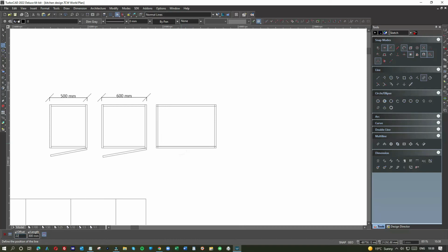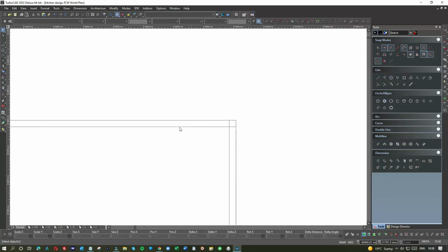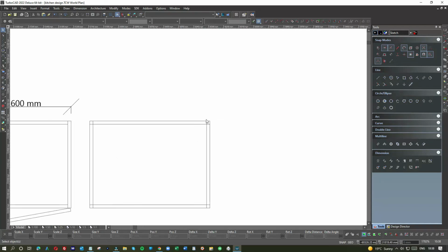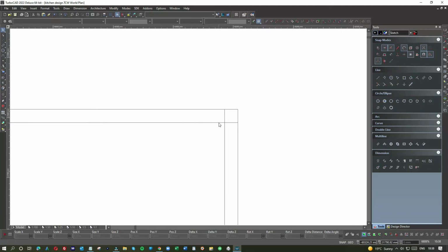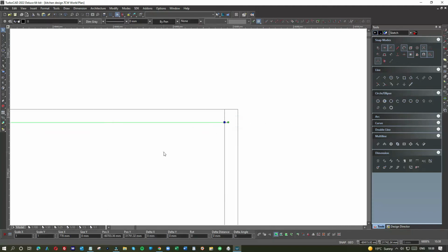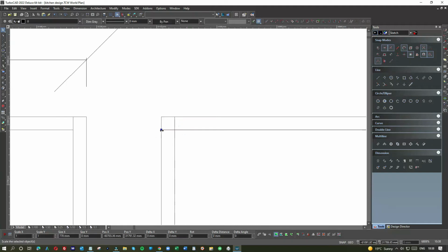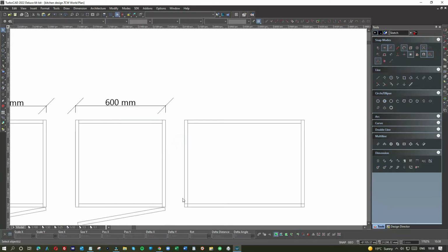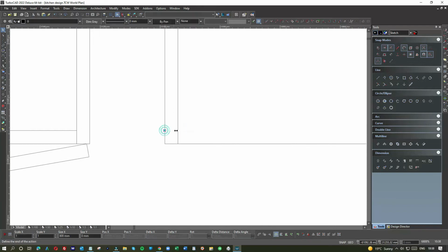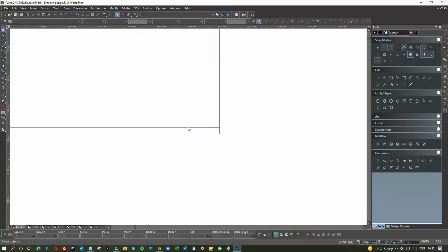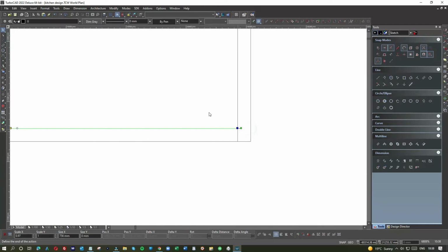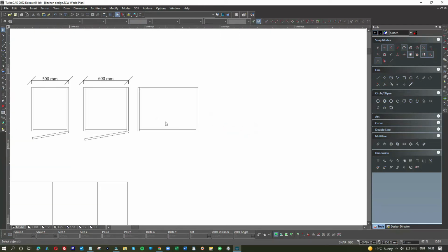tab 22. Now, kitchen units are generally assembled like this. You have two short bits in the middle, and these are full length, in other words the 580. So they would look like that once assembled, with the attachments coming through here, screws, etc. They use dowels, and a kind of catchment tool, one that fits into another. Useful technique. And they use Allen keys, so you don't even need a screwdriver. Right, so that's a basic unit.